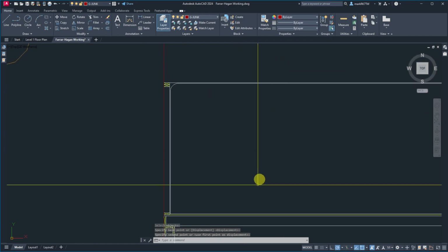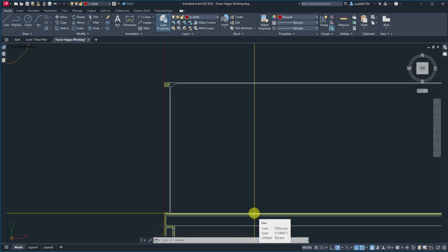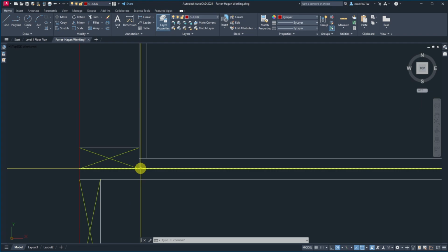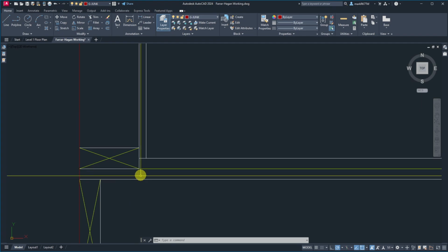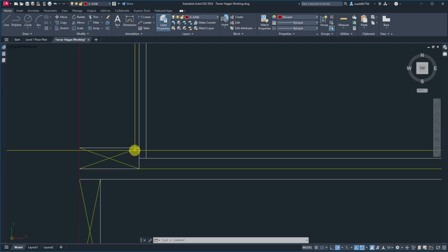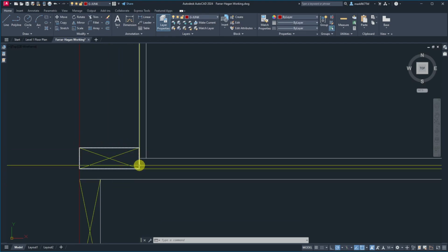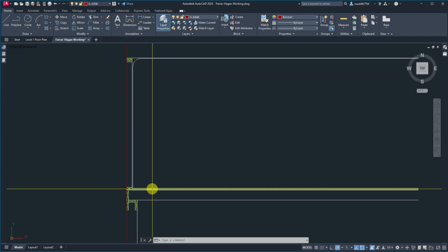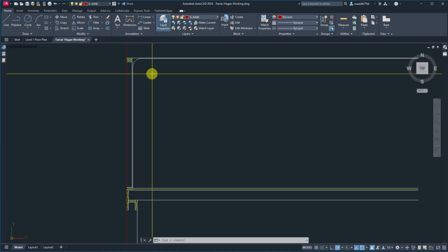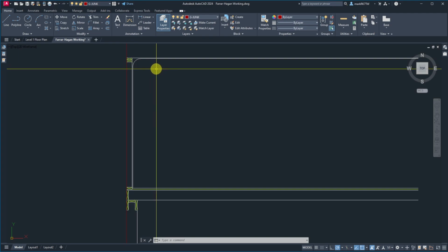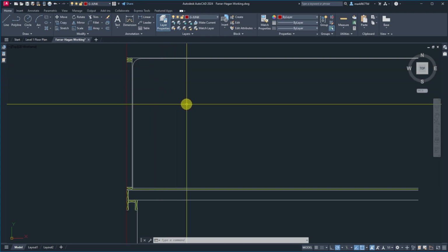In this office, I measured this from finished floor that I'm assuming is 3/4. And this I can pretty much see, but I didn't get a tape on it, so that may not be exactly 3/4 either. This is a weird depth at 4 1/4. That's my stud depth. But the distance from here to the finished ceiling is, I got it written down, 96 11/16.